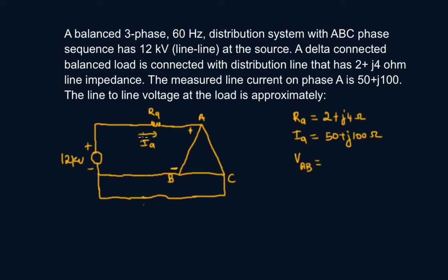So remember this. Line is always bigger than phase, because your line is your entire system, but your phase is only one phase, because we're talking three-phase here. Line is for your entire system. Phase is just per phase. So you know that line is always bigger than phase. If you're given line, to get to phase, you have to divide. If you're given phase, to get to line, you multiply, because line is bigger than phase. So that's how I remember it.